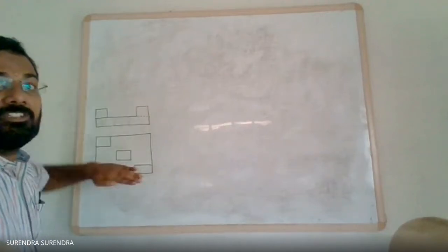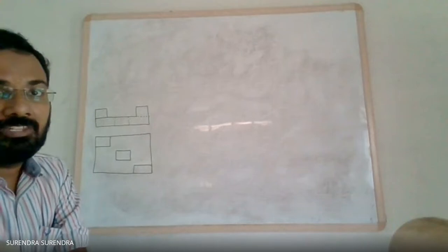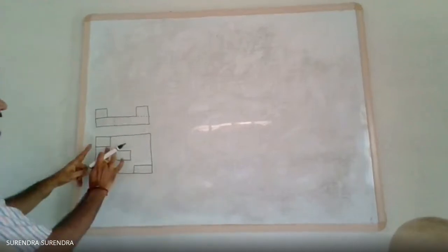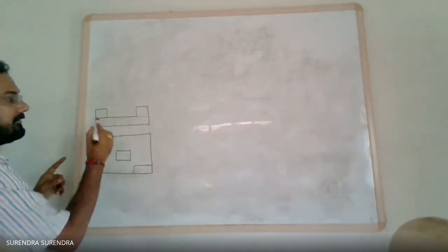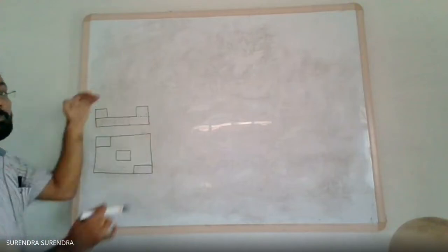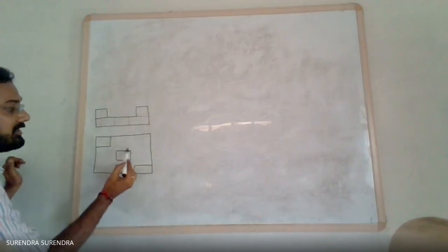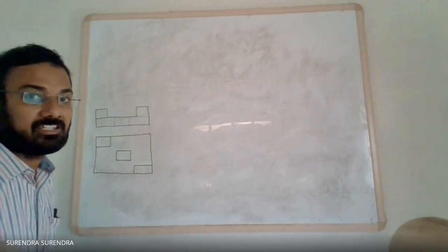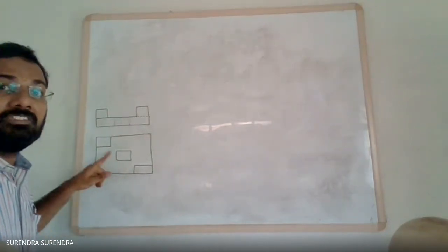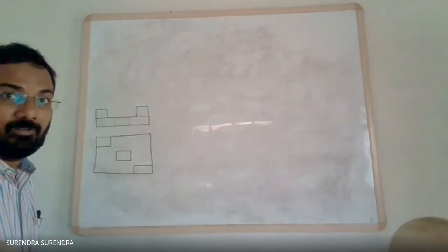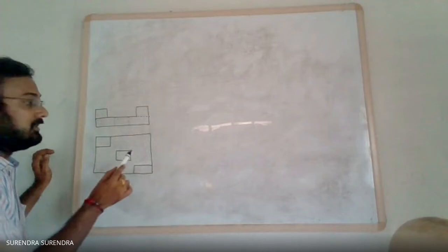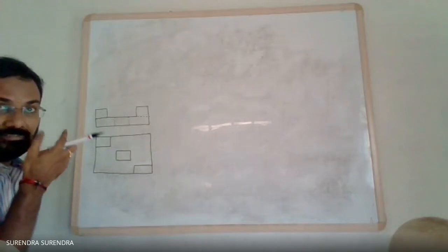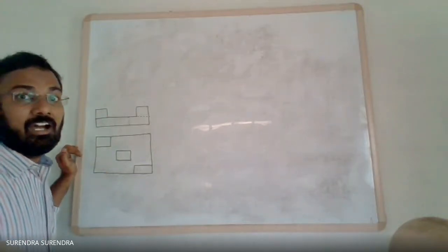Now if you observe the front view, let us compare the front view. How is the front view? These two ends have two projections, relating to these dimensions, these two are the blocks which are projecting upward. And the second one, how is it? Its relation is indicated with a dashed line, so this is a hole and these two are the projections upward. So on a rectangular block, one rectangular hole and two rectangular projections are there. In this way you have to relate, and other details.